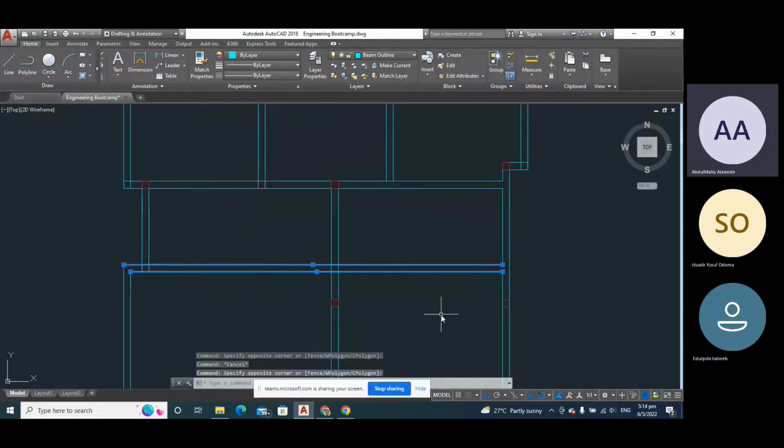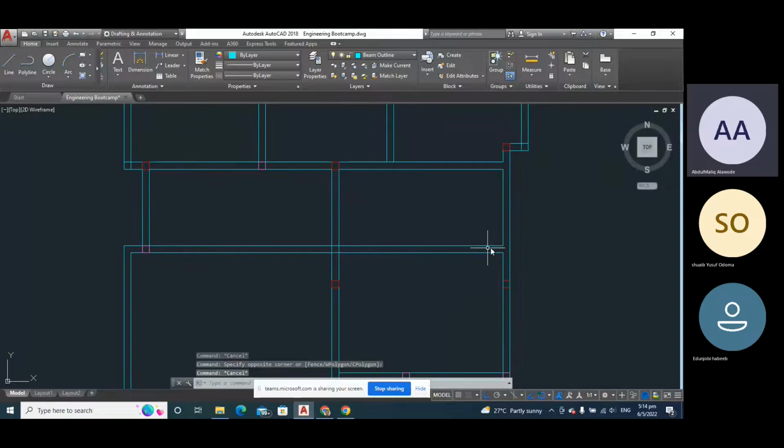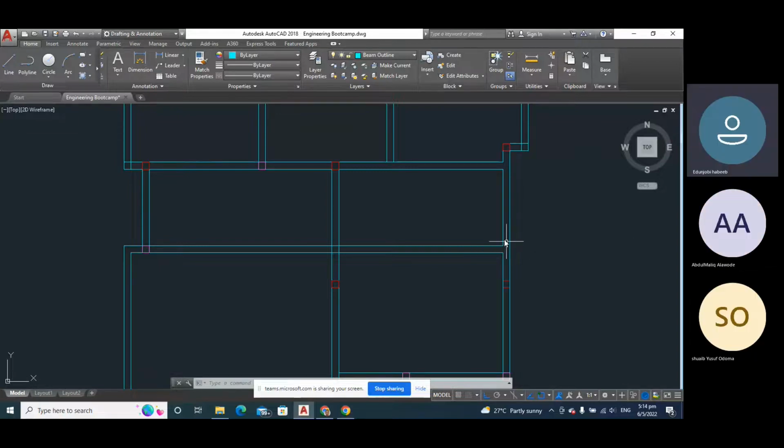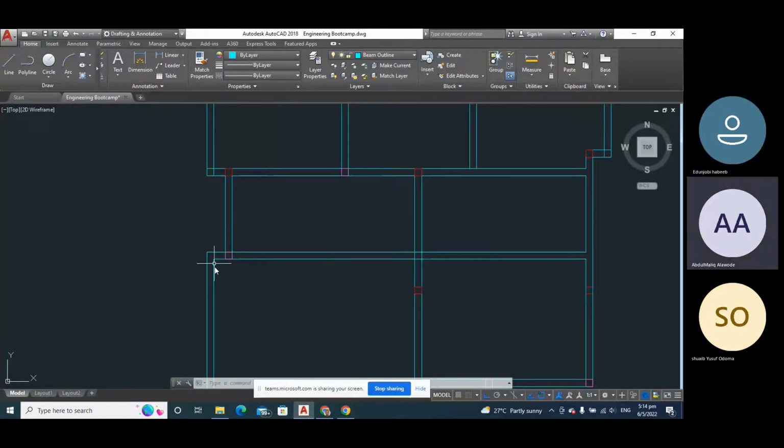Then here, this beam, how is it going to be supported? It's a secondary beam to this vertical beam. Okay, good. This vertical beam that you are pushing is primary. Here? I think it is also a secondary beam to the beam under, sir. Okay, to the vertical beam. Yes, you're right.